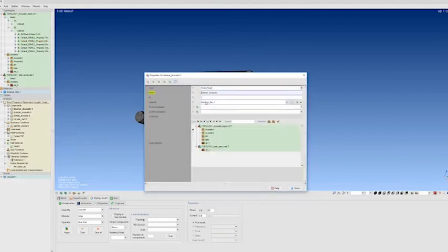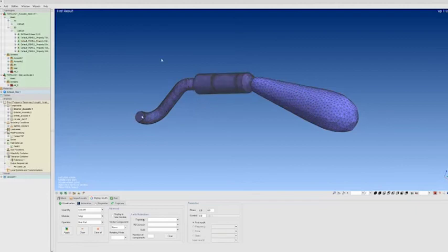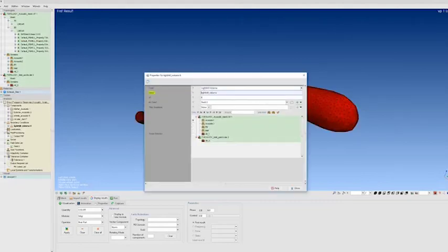Around this, we have a second acoustic domain. This acoustic domain is just there to ensure that the acoustic wave can propagate around the muffler. And on top of that, we have an infinite element surface. This will let all the acoustic waves go out of the system without any reflection, so a non-reflective boundary condition. And this will also allow us to get results on this array of virtual microphones, which are located outside of the mesh that is used for the computation. So this is a typical model for Actran aeroacoustics.